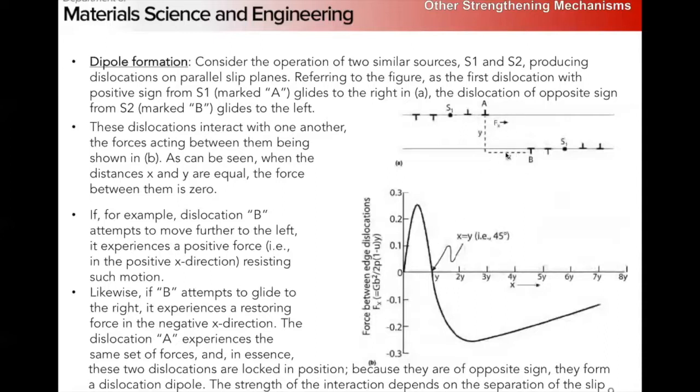And this is called a dipole, right? It's these dislocations whose elastic stress fields are in such a configuration that they're not exerting any force, but moving them farther away will give them an attractive force. To move them closer will give you a repulsive force.